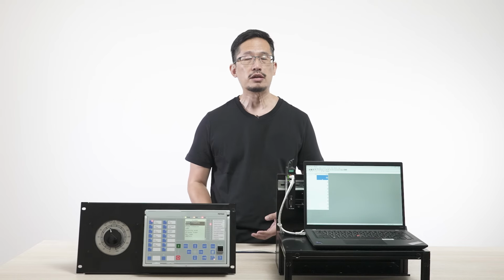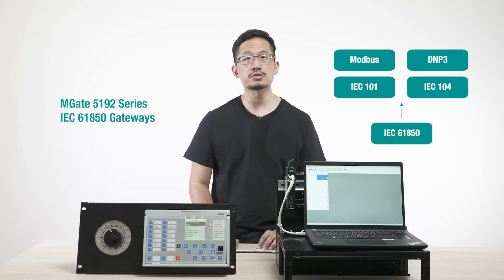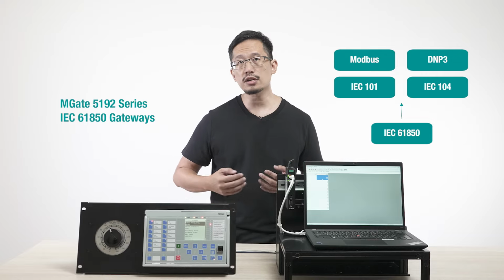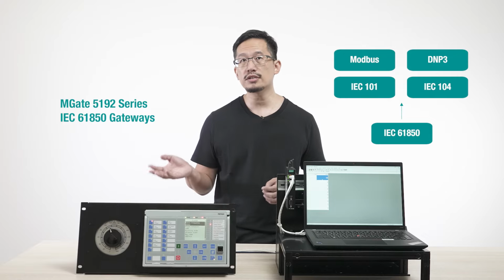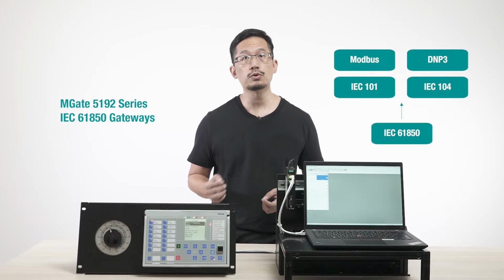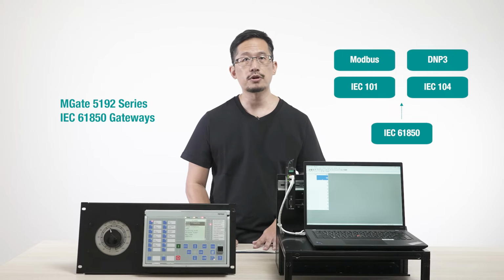So as you've seen, the MGate 5192 gateway makes it easy to convert IEC 61850 to other industrial protocols. It guides you through the configuration process, and it can convert IEC 61850 to Modbus TCP, RTU, and ASCII, DNP3 TCP, UDP, and serial, IEC 101, and IEC 104. And on top of all of this, the MGate supports up to 5,000 data objects, making it perfect for large data communications applications.